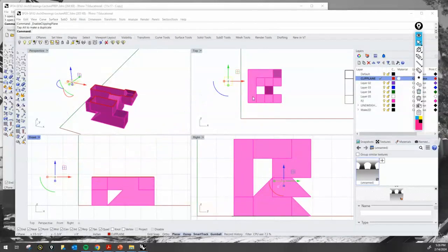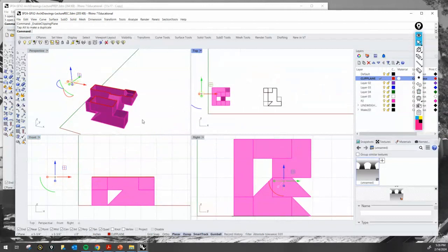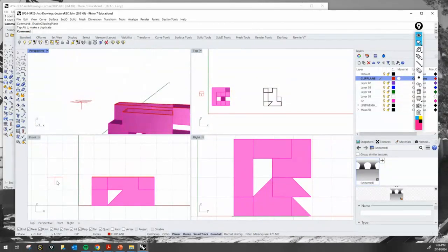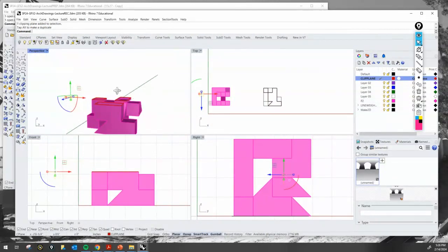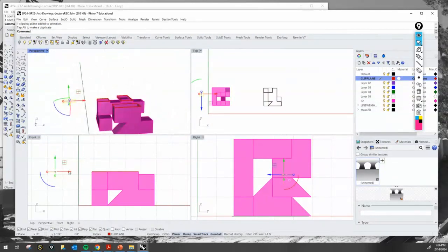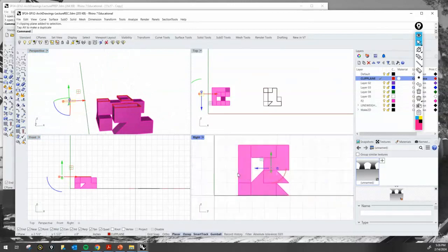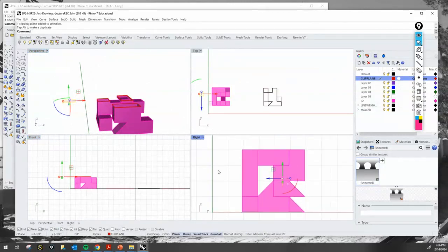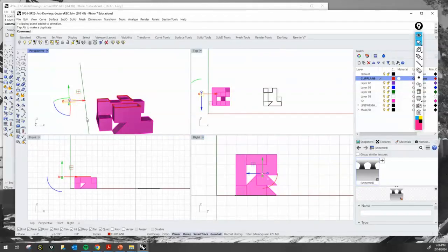And that's what I meant, that you need to draw it. You need to draw the rectangle on the top view, so that we can actually move this right here. So let's do a cut. And for example, right here on the right viewport, you see that it's not enabled. It would be the same deal. So the clipping plane is selected. Let's make sure that you enable the right viewport and you enable it.